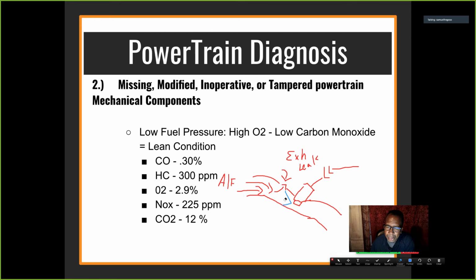What do you mean when you say that? An air pump stuck upstream? Yeah, it's delivering the air upstream all the time. Like, you know, what an air pump does. It goes upstream and downstream. On cold cars, not all of them, but some, it delivers air upstream, that's in front of the O2 sensor. When it warms up, it's supposed to switch downstream, behind the O2 sensor, to the catalytic converter. Is that to warm up the O2s? Yes, exactly.